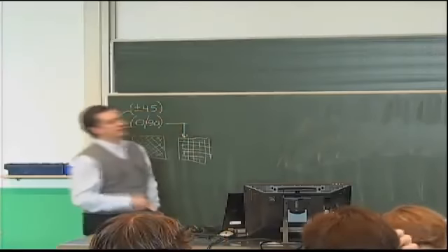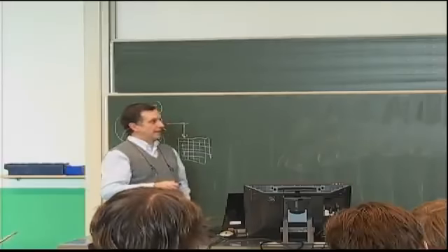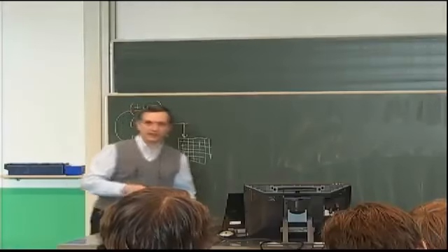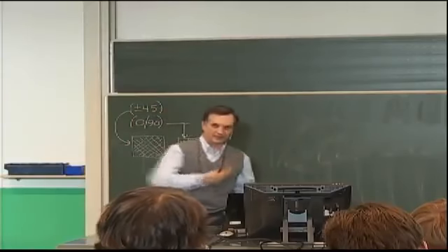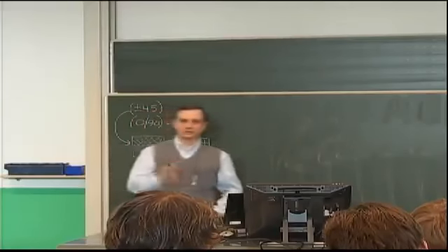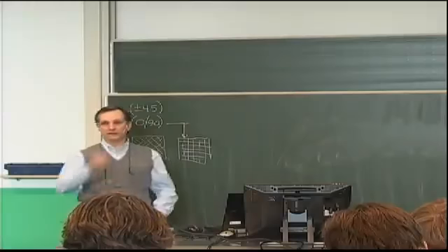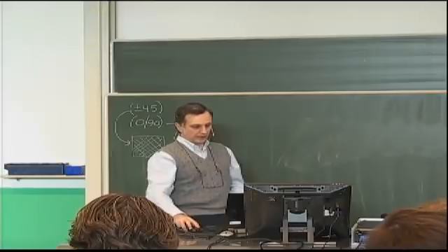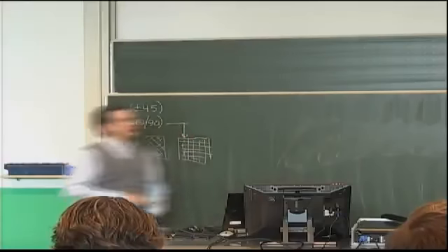Is because, first of all, walking loads, step loads, especially if you have high heels, which is quite concentrating the load, are essentially a floor with a point load. More importantly, impact. Impact is, of course, a dynamic problem. We'll talk about that in the next quarter much more. But as a first cut, especially for a series of impact problems called low-speed impact situations, you can start the solution by trying to solve this problem of a point force acting on an anisotropic plate. And we are assuming simply supported conditions.